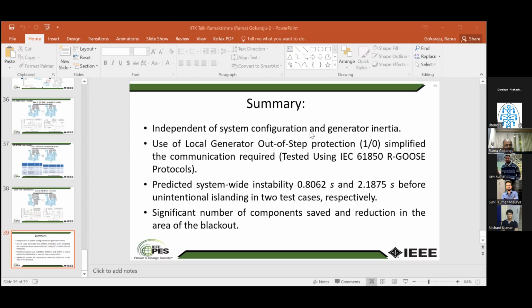Okay, thank you. So locally, we would have to do the additional things on the system. And that's a very good point. Certain portions from the computer relaying text I put in verbatim, but in between those points it is also mentioned there, if you look in the Phadke and Thorp text. So within that system, we would have to do the local protection as well. And the frequency stability, the over voltage, under voltage, those things also have to be met.